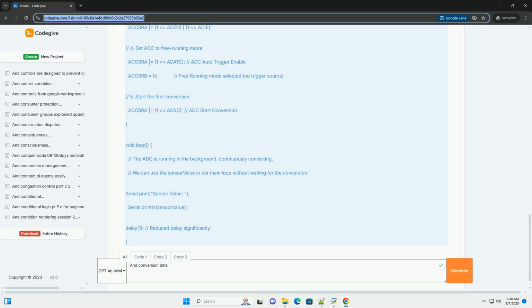The conversion time is often provided in the ADC's datasheet. However, you might need to calculate it based on the specified parameters. Here's a breakdown of how to estimate the conversion time, particularly for SAR ADCs, the most common type. Acquisition time, T_acq: datasheets often provide a minimum required acquisition time. If not, it can be estimated using the RC time constant, T_acq = 5 * R_source * C_sample.